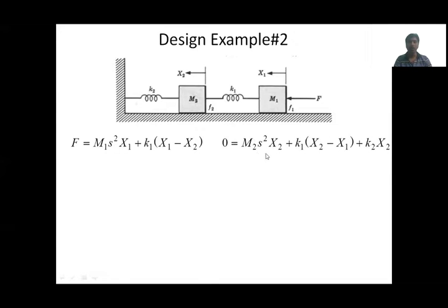Now from these two equations we can get, after moving this K1 x2 to the left side, this expression. Similarly, if we move this K1 into x1 to the left-hand side, we get it like this. This is useful for finding the relation between different nodes like the applied force, x1 and x2. Here in these expressions, or in this model, you can easily say what the variables are.